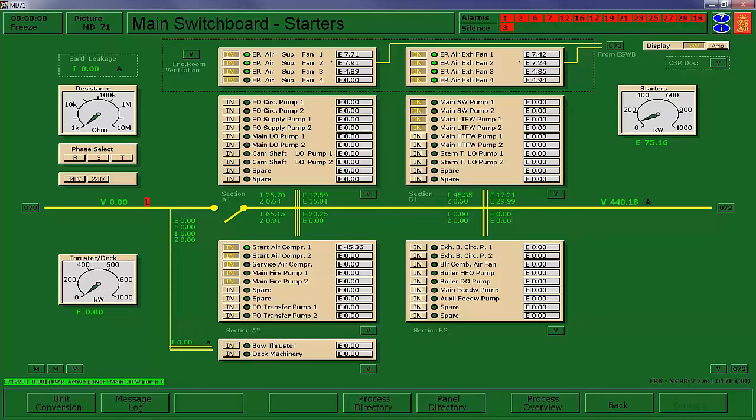All right, so I'll go ahead and start it. The first thing we're going to do is put on the, what are we going to need? Well, we're going to be getting the high temperature fresh water system ready, and we're not going to use these pumps per se, but I want that system operational and ready to go when we're finished. So we'll put power to the main high temperature fresh water pumps, the exhaust boiler circ pumps, exhaust boiler compression air, combustion air fan, heavy fuel oil, diesel oil pump, all of those, main feed water, auxiliary feed water.